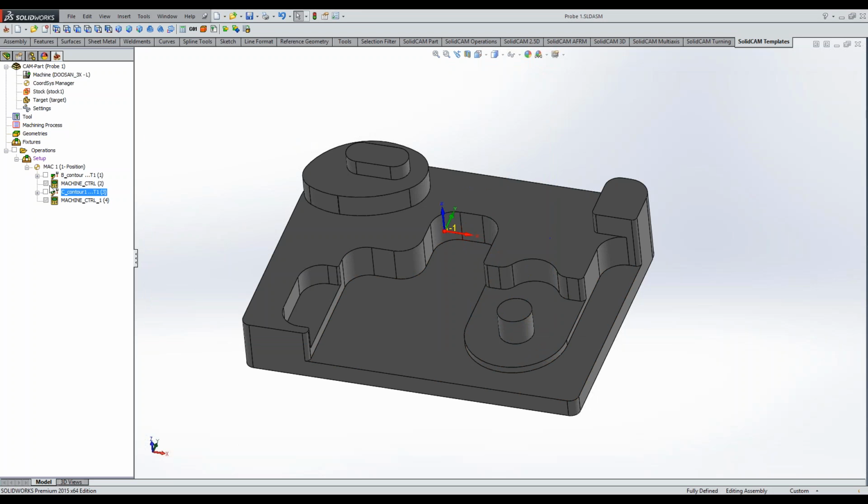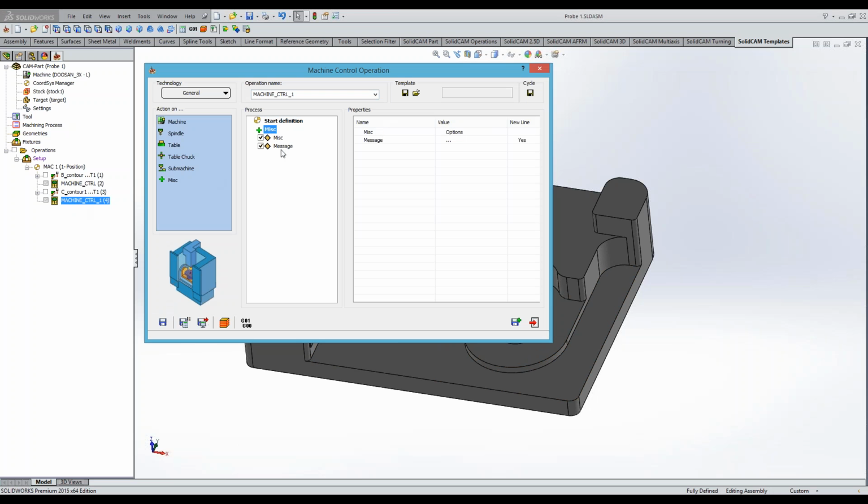And again, the variables 135 and 36 are updated to this new position. Yes, but I already saved them. Now, again, a new machine control operation with a new message. I will save the new center in X and new center in Y in new variables. And at the end, I will calculate the last center in X minus the first center in X, and I will get the distance between them in X.